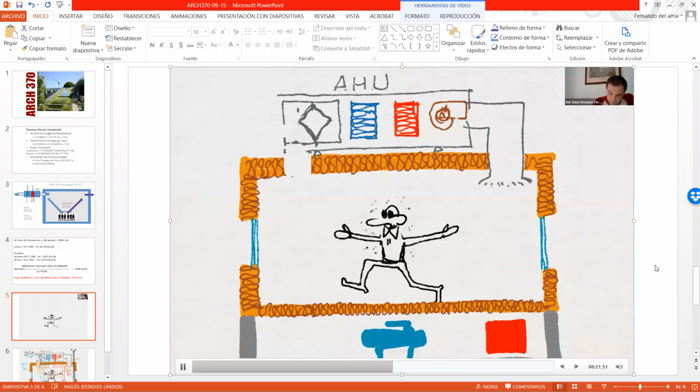And now, instead of getting rid of this air, we are going to recirculate this air to the air handling unit again, and that's why we have this heat recovery. Okay, so we have this. We have another grill somewhere, and we will get rid of this exhaust air, but through the heat recovery. And this is what we are going to do now.